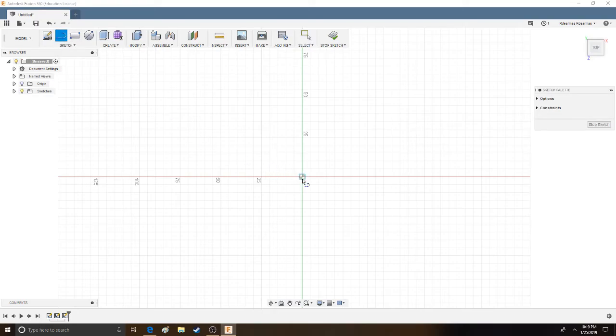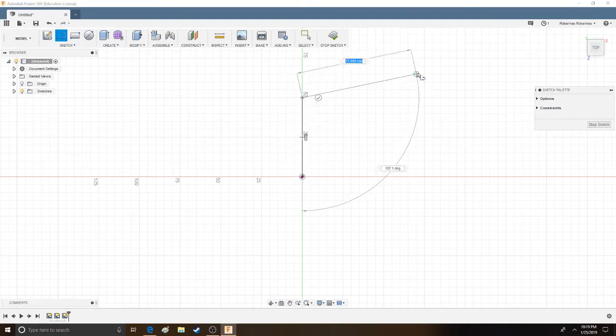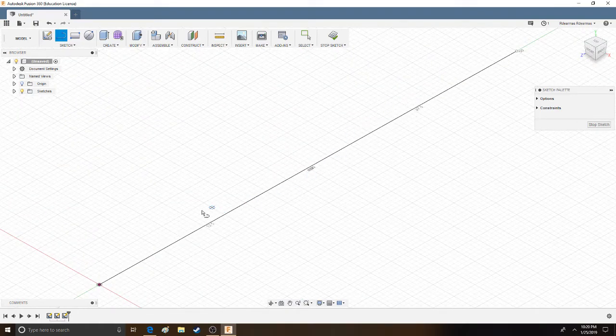So using the line tool, we're going to be selecting the middle and going up to 50 millimeters. Now that we're at the top, we're still attached to it, but it placed the first point to the second point. So this right down here to up there. So now we're going to stop this and we're going to click on this. So this green check mark instantly stops our line from continuing and leaves this line in position. So this right here, this is the first line created in Fusion 360.